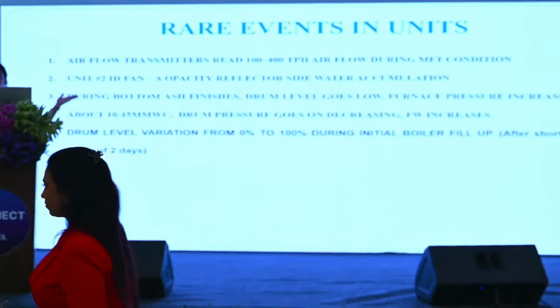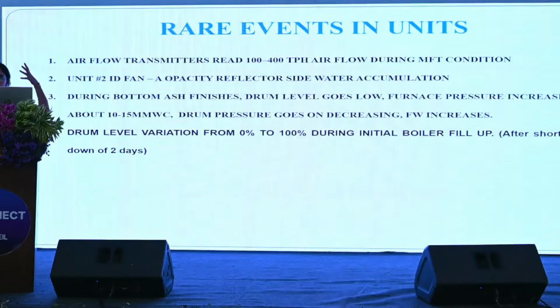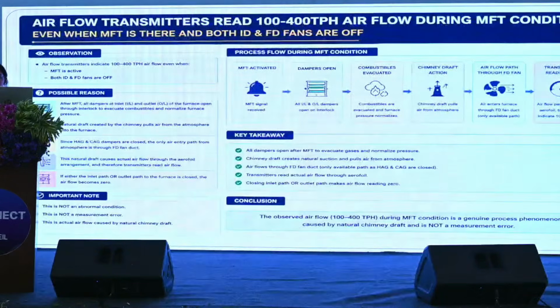Okay, this was because the chimney height is 200 meters and because of that natural draft, this transmitter was reading. Likewise, we have another 2 to 3 case studies, but because of lack of time, I would like to finish it here.